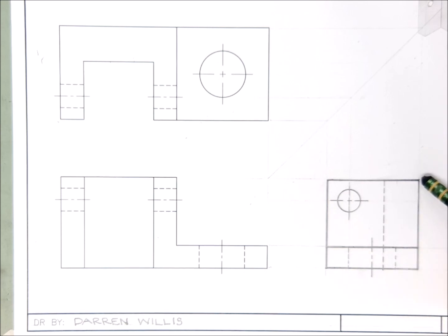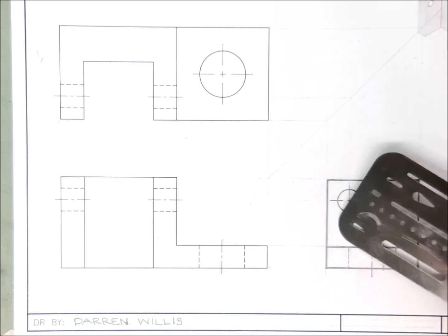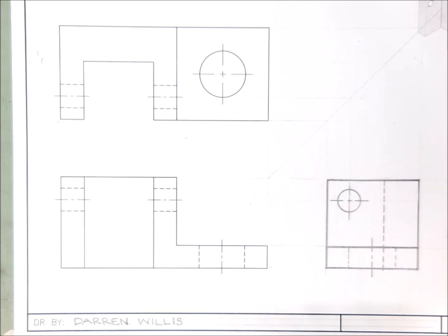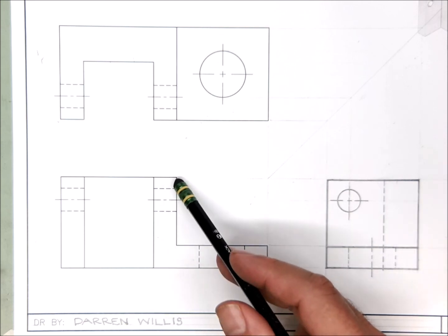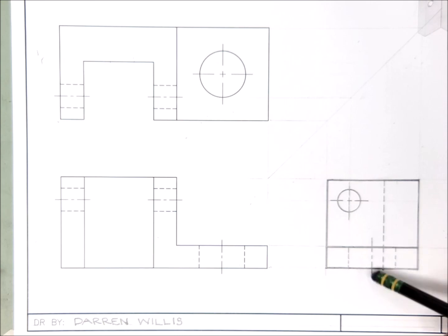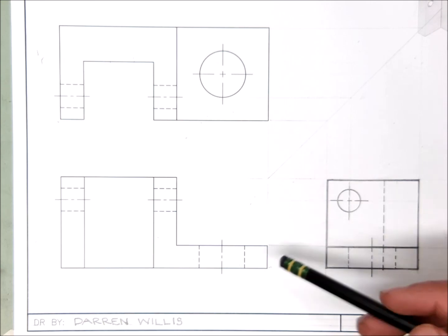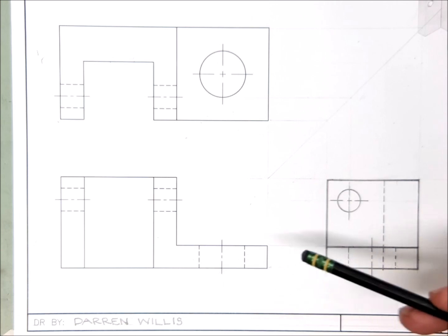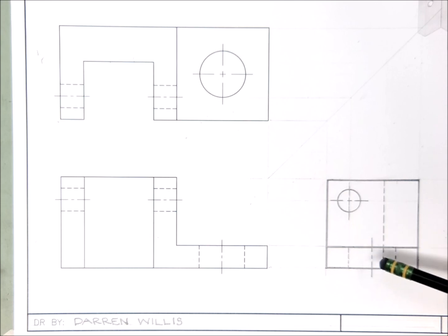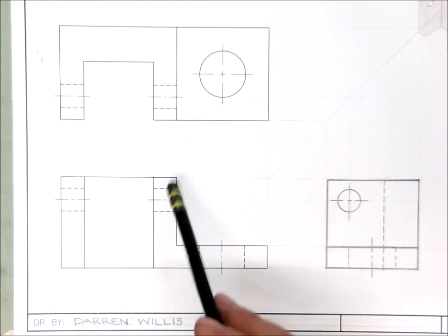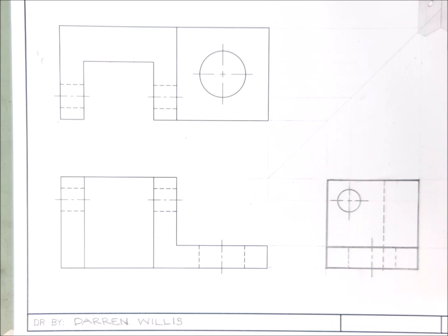If the corners don't match precisely, you need to get in there with the shield and make them perfect. Because this is not a sketch. It does matter that things are drawn with accuracy. Right? Are the hidden lines drawn correctly? Well, look at the hidden lines over here to see how they should be drawn. Is your center line drawn correctly? Make sure it looks like this center line going through the tunnel, not like a center mark. You put the mark, the two crossing center lines, on a circle, not through the tunnel. Okay, so use what I've given you as a guide as you're looking to see how the assignment is and how close you are to having it finished. That is our completed drawing for assignment 3.3.